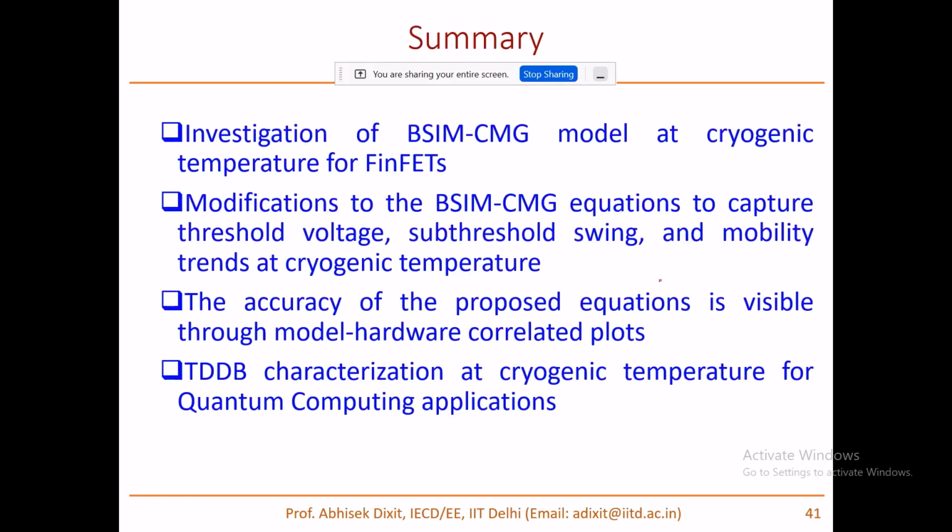Yeah. So what we have done in the last two plus years is look at how cryogenic CMOS performance is different from room temperature CMOS performance, and this is all industry standard, production-ready technologies from various integrated device manufacturers, foundries and so on. So we looked at these short channel devices, 10 nanometer, 7 nanometer and so on, digital CMOS type devices. And then we looked at the industry standard compact models which are used for simulation of circuits by designers. BSIM CMG, for instance, is the industry standard model for FinFETs.